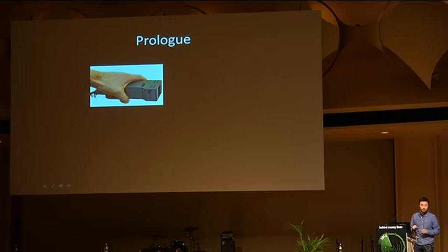These systems are called SLAM. But the solutions we found were either too slow or not precise enough. The geometry was quite rough. But at some point, one of us suggested to use a Kinect camera instead of a laser rangefinder or a video camera. And we found the algorithms we needed to build up a 3D model out of a Kinect camera. But we also had problems with the computation speed. We had to handle so much data within a couple of milliseconds that the CPU couldn't keep up.